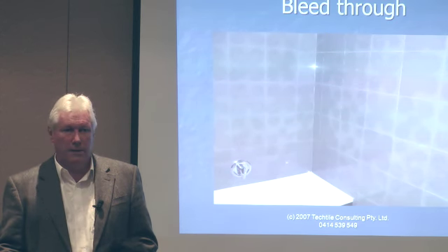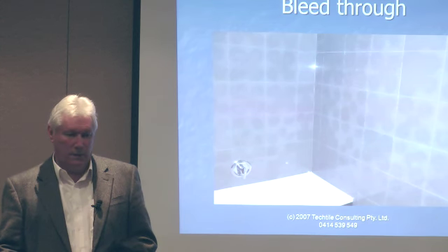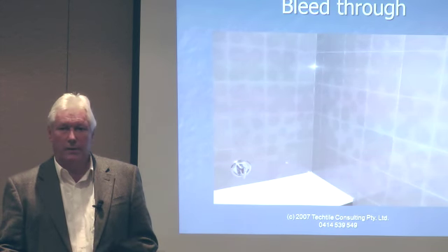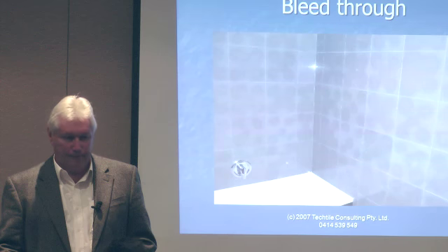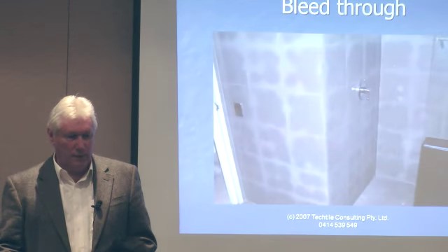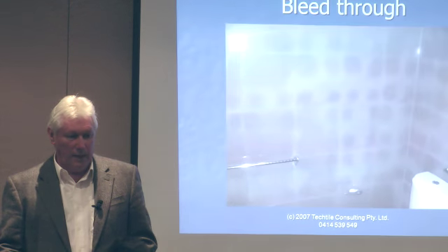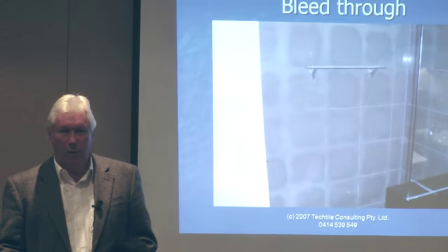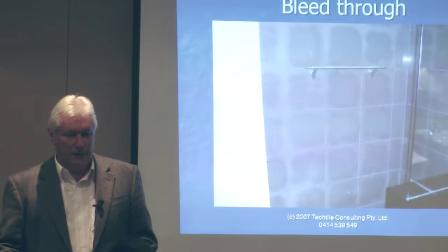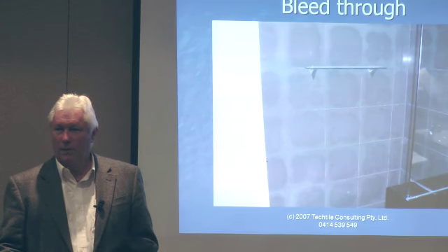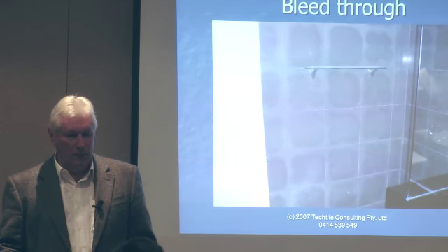So after a few months, they started to notice they've got wet spots, and you end up with a pretty big court case to try to solve something like that. To show you the extent of it, this was the guy that was putting on mostly with 4 spots. And we had another guy there with 4 spots, and this bloke, we called him Big Blob Man, because he just tended to put the tiles on with a big blob on the back.